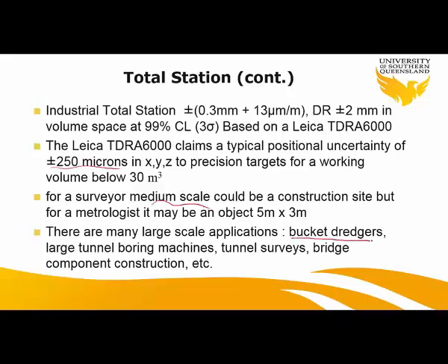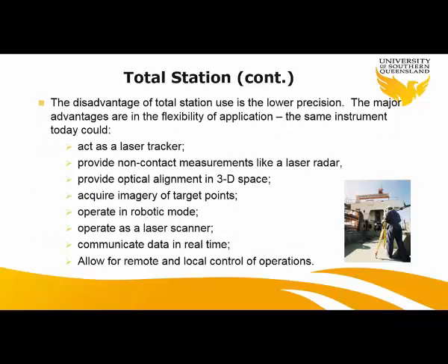Examples are bucket dredgers, large tunnel boring machines, tunnel surveys, and bridge component construction. For all of these applications, you can use a total station for both measurement and monitoring. The disadvantage of the total station, obviously, is its lower precision compared to the other measurement devices or systems that I discussed. But there are some advantages, which are mostly about flexibility and portability.